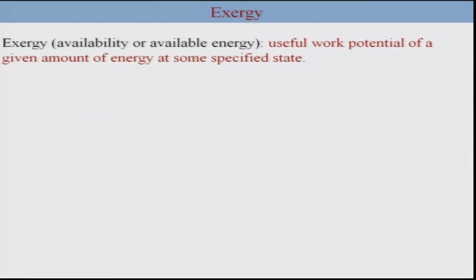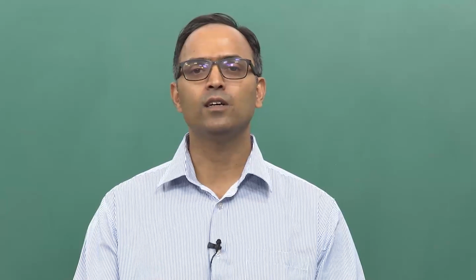So, in other words, if we describe a system and ask what is the maximum amount of work which we can extract out of the system, then we need to do certain analysis, and in order to do that, we will define a term called exergy. So, our practical interest would be to find out the maximum work which we can extract from a given system having a certain specific state.